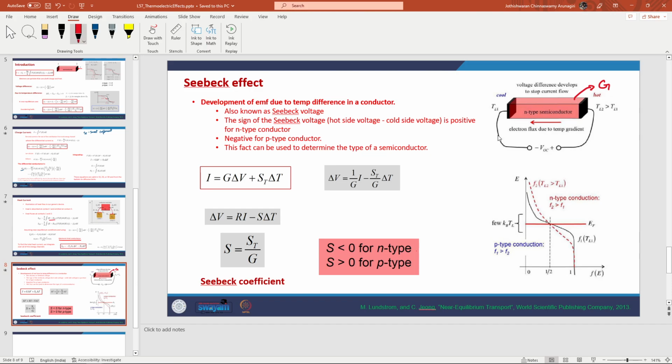However, because of thermoelectric effects, if this were a P-type material, that current would have been lesser. So that is equivalent to applying a reverse voltage independently and reducing the effect of this voltage. So the Seebeck effect can also be interpreted as an internal potential in the device. For an N-type material, the Seebeck voltage is positive. For a P-type material, the Seebeck voltage is negative.